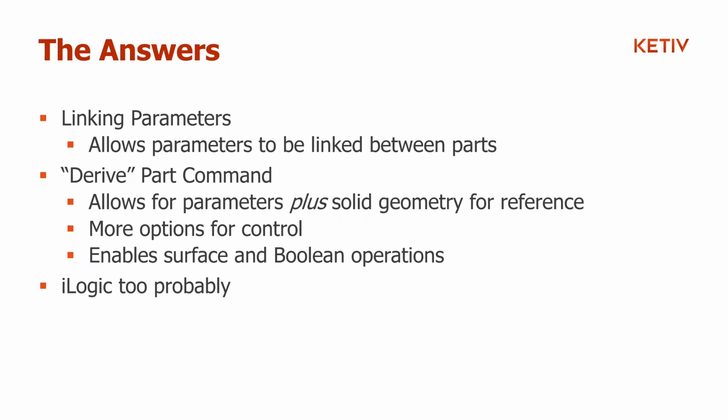And the meat of this conversation I want to talk about is the derive part command as well, which not only allows you to transfer parameters into another model, but it also allows you to link the solid geometry into the model as well. Okay. And that overall is good because it has everything that linking parameters could do for you, plus all of these extra controls, and it enables a lot more advanced workflows.